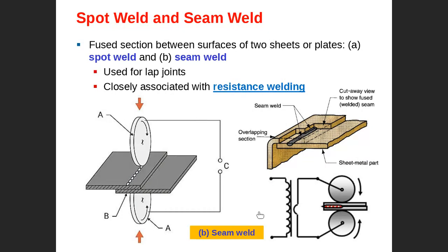Someone asked what the interval depends on. It depends on the on-off switching. If you switch on and off slowly, you get a big interval, but if you switch on and off quickly, you probably get a continuous line. So the line depends on the frequency of the current you apply: on-off gives you a big or small interval between spots. So we call it seam welding. It is exactly like spot welding, but continuous spot welding, so you get a line instead of a spot.